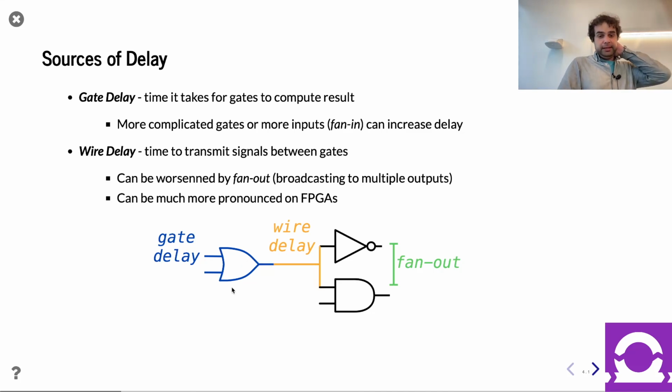Even the gates themselves, the delay depends on the technology you're using, right? So for example, in an ASIC process, usually you hope your gates are only 2 or 3 inputs. Too many inputs makes it a lot slower. However, in an FPGA, which has LUTs, maybe 5 or 6 bits, you actually pay no latency penalty until you go beyond 5 or 6 inputs. You're actually encouraged to use larger gates. So you can see already that the complexities of which logic gates to use should be handled by synthesis tools and the CAD tools.